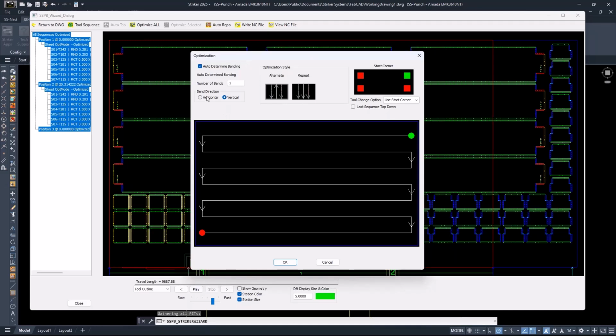Now, when it comes to optimizing for cutting or punching, but punching in particular, you can't just say, hey, I want to optimize this tool sequence and I want to start with this hit and go next closest, next closest, next closest, because you could find yourself with tool hits scattered around, so it starts up here and then ends up snaking down here, and you optimized a strip through the center of your sheet and didn't optimize anything else. So the sheet has to be looked at in different sections, and different software products handle that differently.